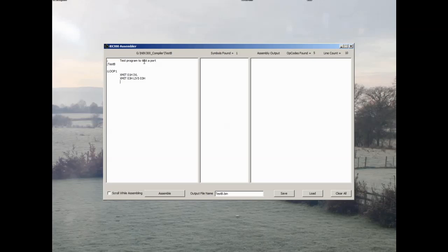That's set the address and the actual data we want to send, and then to make it toggle rather than just setting something and it staying the same, so we can see if it's actually active, we want to send a different value. We want to send it to the same address, so we'll repeat the first setup instruction. So we'll set up the same device and then a different value to send so that we can see hopefully the bit toggling. So in this case, again, an arbitrary value of 4 to the same place, and again we'll put an arbitrary number in there as well.